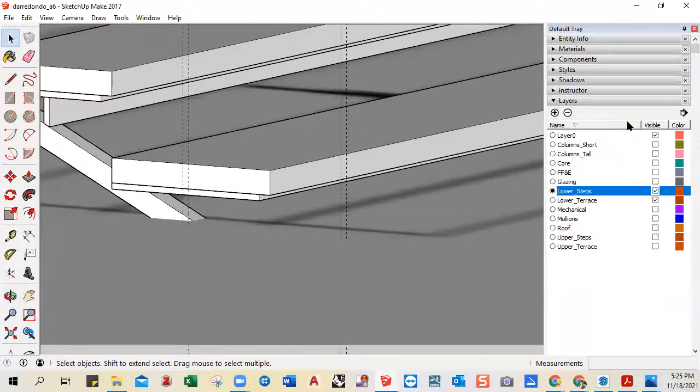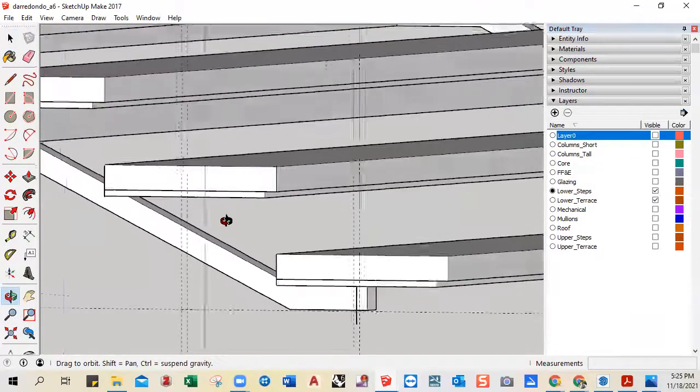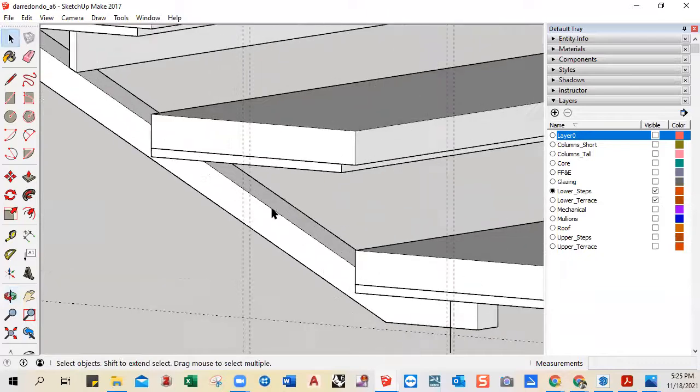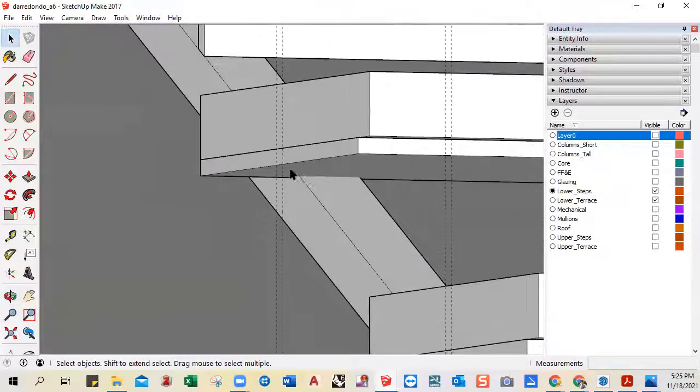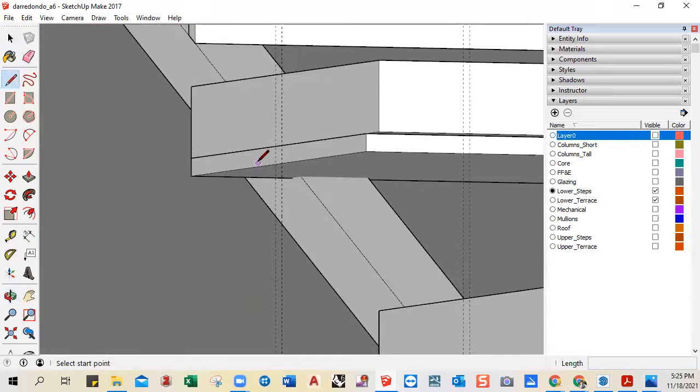Now here I'm going to hide that layer of the floor plan. I'll do the same thing here. Just going to bring the lines across. So L here on the red axis holding Shift, align it to the edge, space bar, same thing, L for line, coming back on the red axis, holding down Shift, bringing down my cursor so I can align it there.